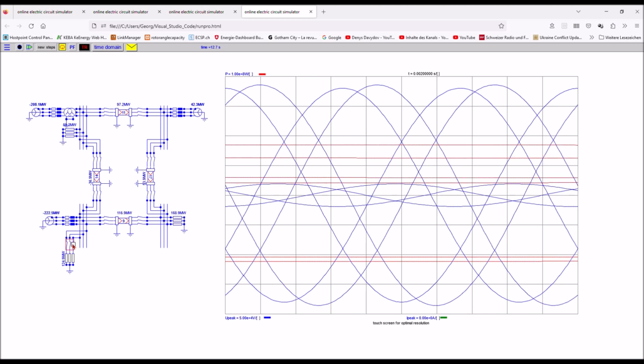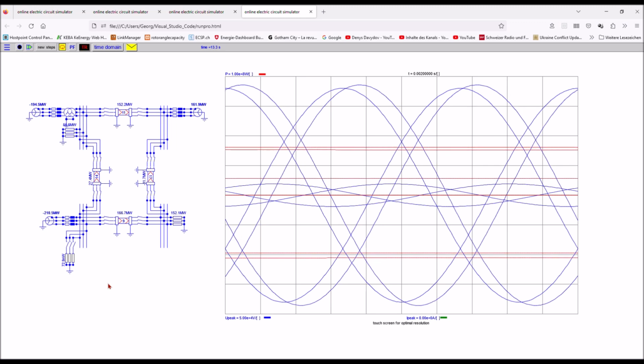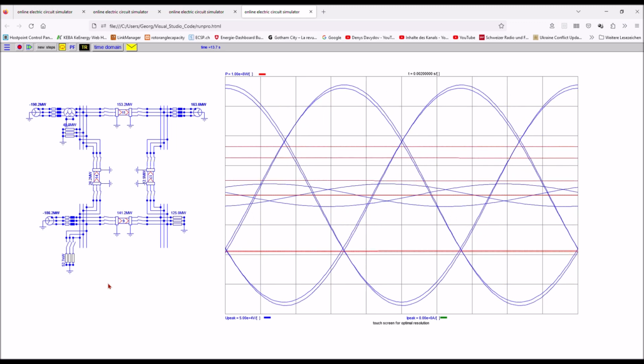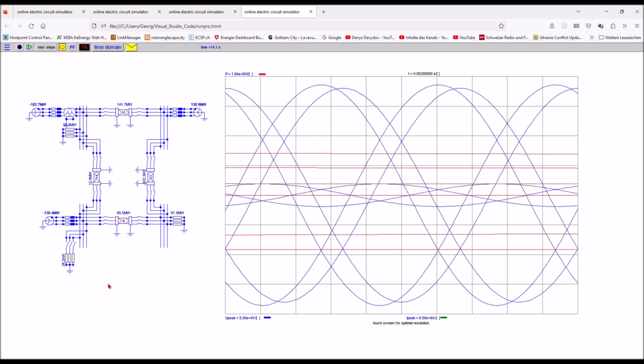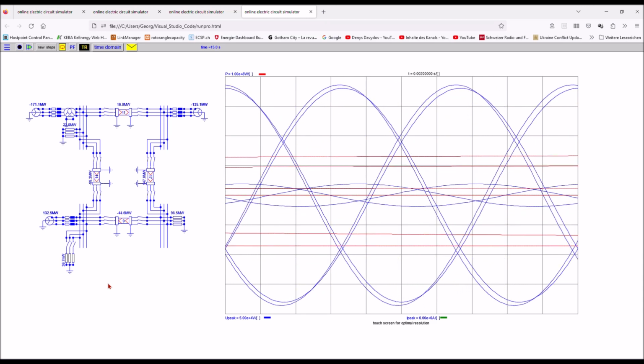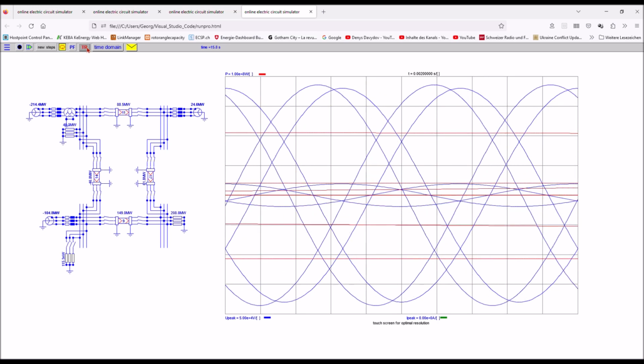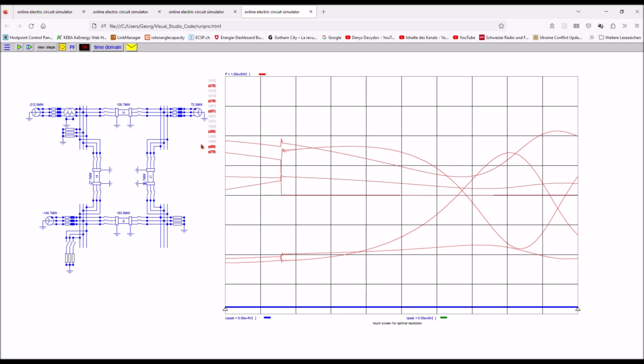The system loses stability. The infinite bus takes the entire power which is generated in the grid but is not needed anymore due to load rejection. I can now see the whole event in the transient recorder by watching the transient recorder function, where I previously already removed the traces which I'm not interested in. This is a very important function in order to understand the behavior of your network.